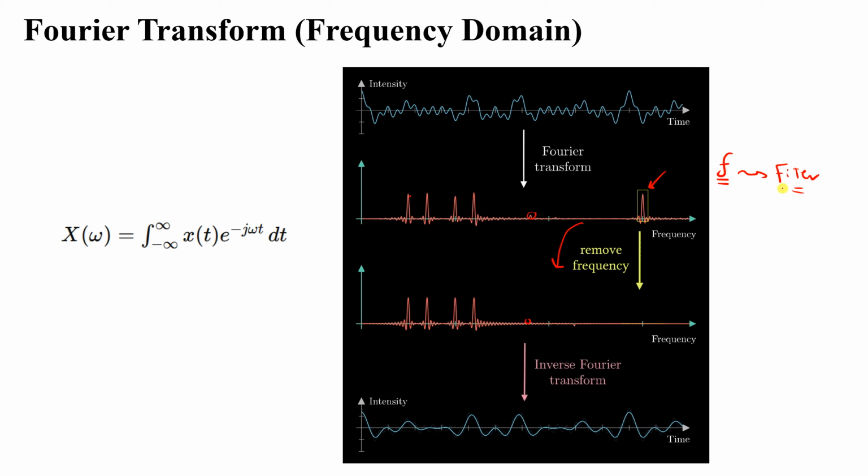But this filter, this is a low pass filter that will pass small frequencies and kill high frequencies. That's why these frequencies are passed normally. However, high frequencies like here, you will see that they are almost dead due to the effect of a low pass filter. Okay, so we will have this signal.